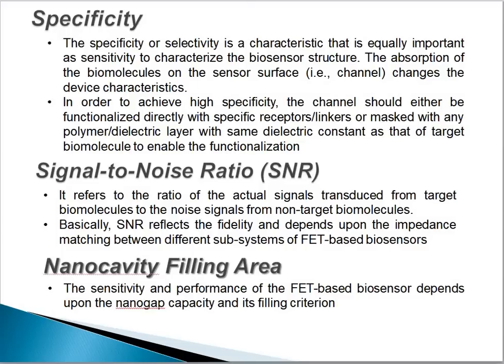Next factor is the nanocavity filling area. The sensitivity and the performance of the FET-based biosensor depend upon the nanogap cavity and its filling criteria. It must be partially filled or fully filled. It also depends upon the biomolecule orientation, because biomolecule orientation changes the dielectric constant of the target biomolecule. Despite the shape and size of the target biomolecule, the device analysis is generally carried out with an assumption that the nanocavity is fully filled or partially filled with the target biomolecule.